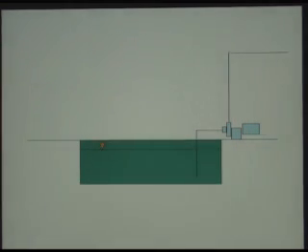Obviously, if you've got a reservoir, a tank, a pump, or a pool of some nature, that the fluid level is below grade and it's open to the atmosphere, the liquid level is here inside the suction pipe, and there is no way of pushing it up into the pump suction. This is a non-priming system, so that means you have to form some external source of prime to be able to get the fluid into the pump so the pump can operate. And you do that, one way is to pull a vacuum on the discharge line so that it actually pulls the fluid up through the pump and up to about this elevation.